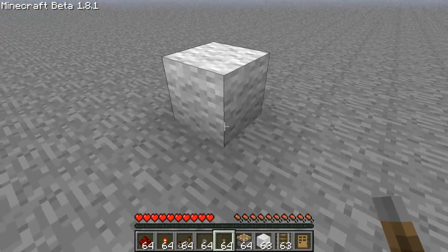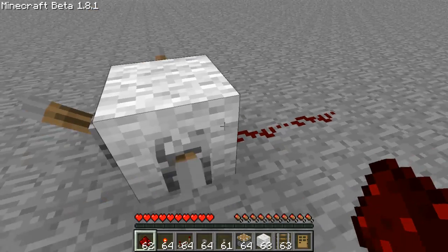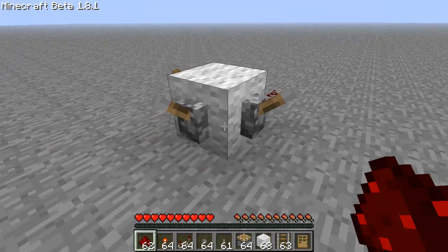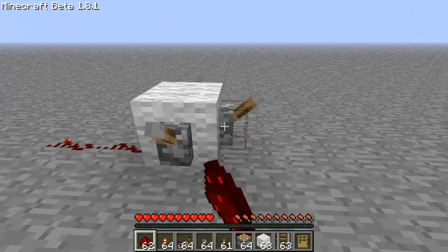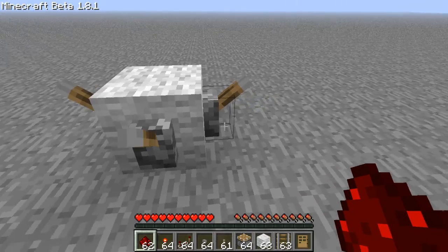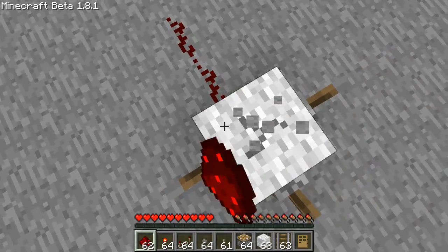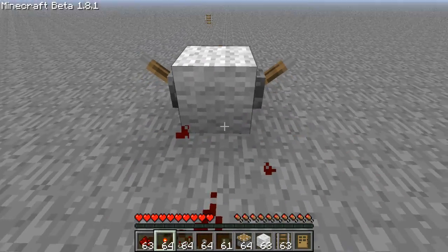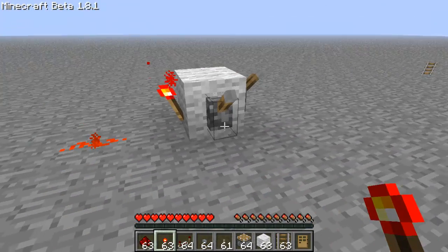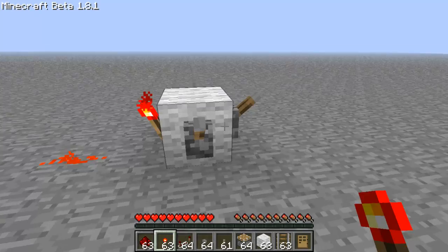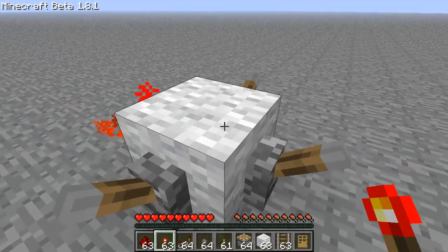There's something called an OR gate. So say you have 3 inputs and 1 output. No matter what switch you turn on, the output will be on. So it's this one, or this one, or this one. And that's why it's called an OR gate. A NOR gate is just an OR gate with an inverter on the back. So, not OR. So this is on, that's off. This is on, that's off. Pretty self-explanatory.